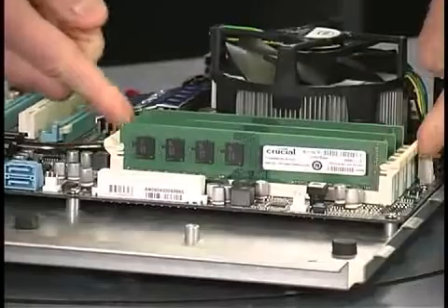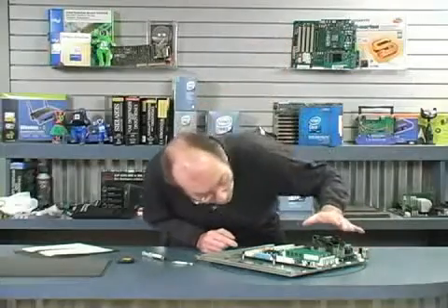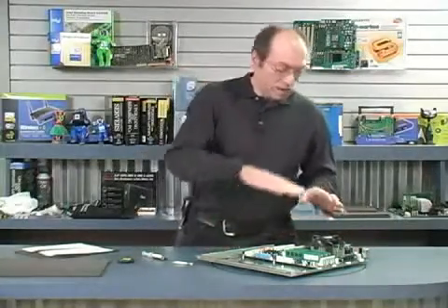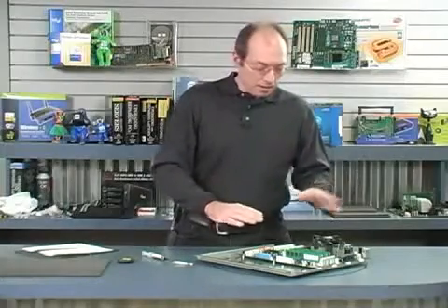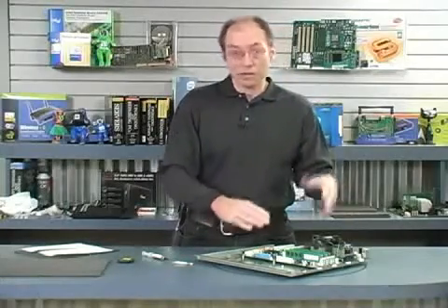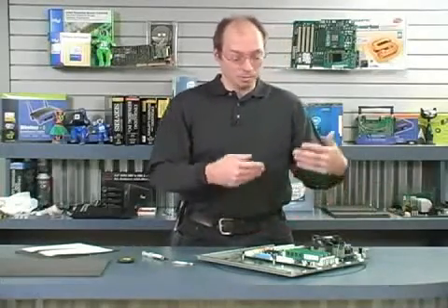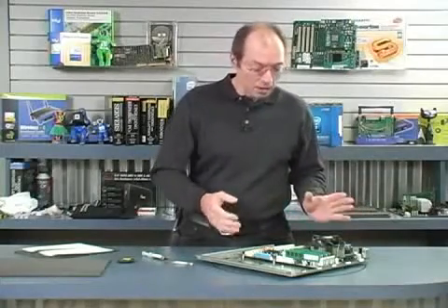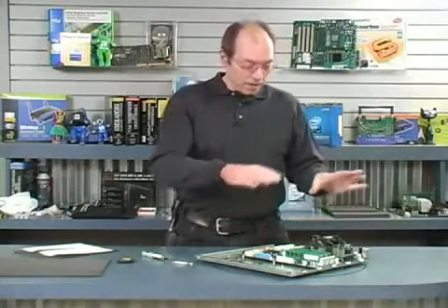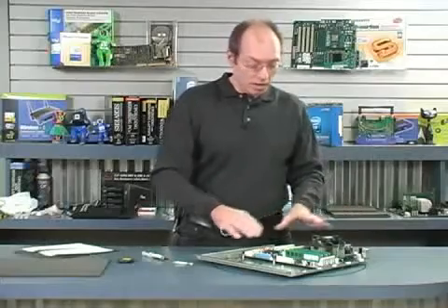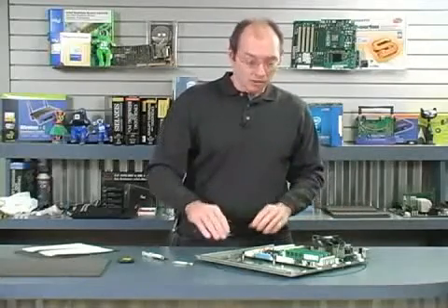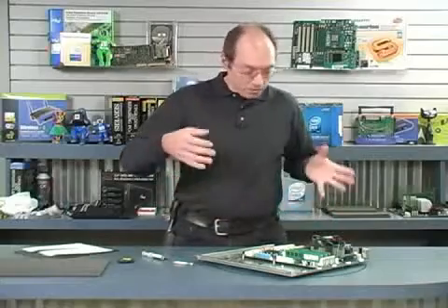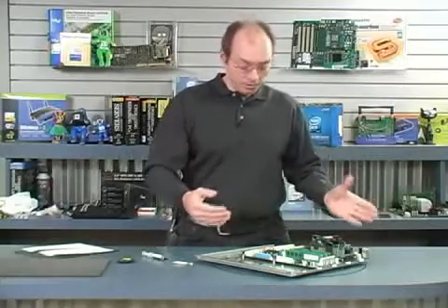And again, make sure they're all in place. You might want to take a closer look, make sure that all the modules do seem to be fully seated. We don't want them on an angle at all. If a module is partially installed and you power the system on, you risk burning the modules and damaging the motherboard as well. So, at this point now, I have the processor and heatsink installed, I have the memory installed. I can now take the motherboard out of this tray and then install the fully loaded motherboard into the system.